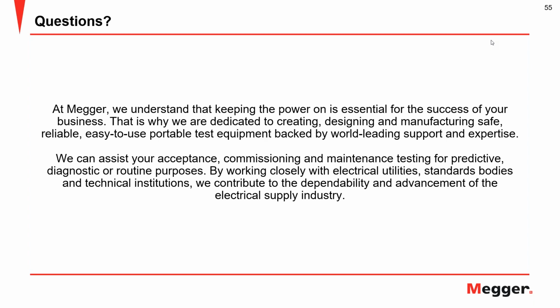The offline PD test, done in the conventional way, is the method for power cables, and it's the only method where you can really do a condition assessment, because you're actually measuring values that can then be used for trending, replacement programs, all kinds of things like that.